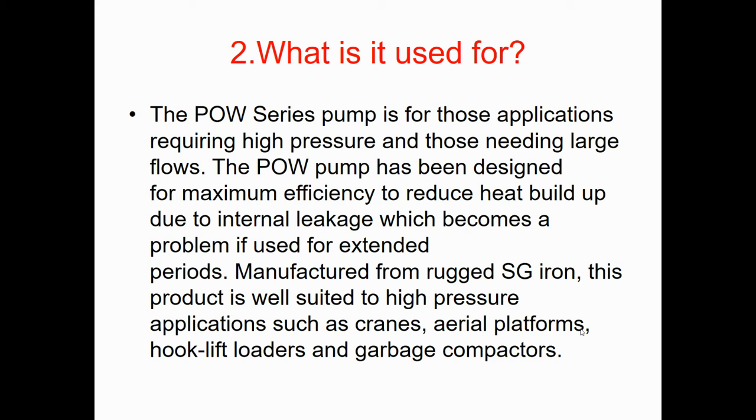Now the hydraulic pump in general, it's called hydraulic pump. Sometimes we call it the gear pump. This will depend on either classified depending on the material we are going to pump with, or depending on the working principle. So the working principle of this pump is having two gears, the drive gear and the driven gear, going to rotate together, generating two areas of pressure within the pump, and thus we're going to have positive and negative pressure areas, and thus the flow of the hydraulic is going to be achieved.